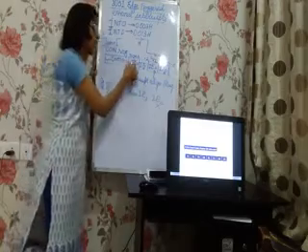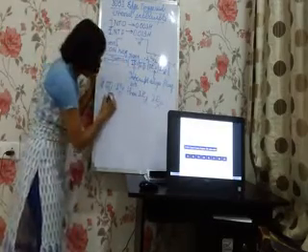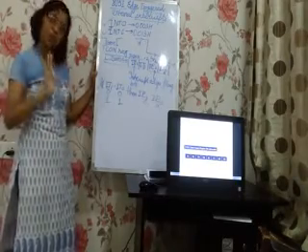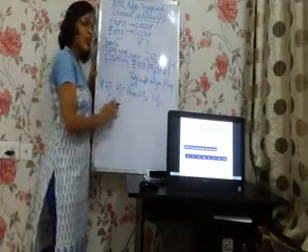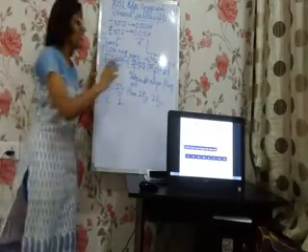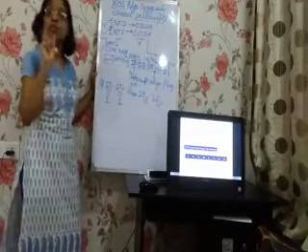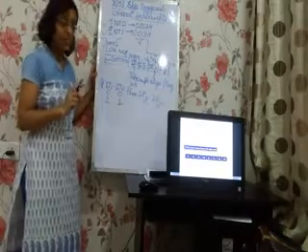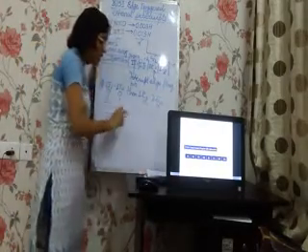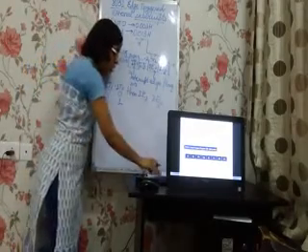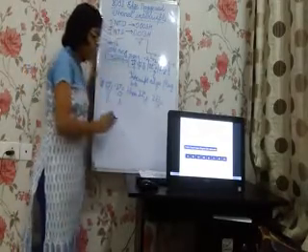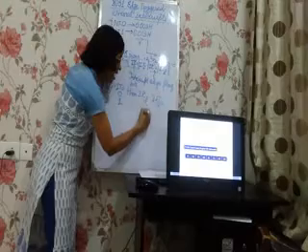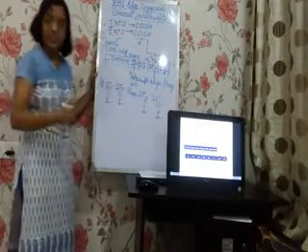So for these two bits to take effect, IT1 and IT0 should be 1-1 or any one of them should be 1, depending upon your application. If any one of them or both of them are 1, only then the status in IE1 and IE0 will be called a valid status. So if INT1 gets defined as edge triggered interrupt, and INT0 gets defined as edge triggered interrupt, then in that case IE1 and IE0 will be made 1.